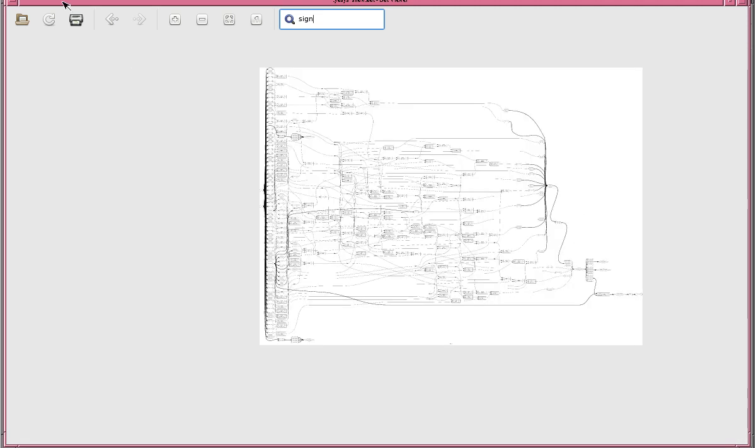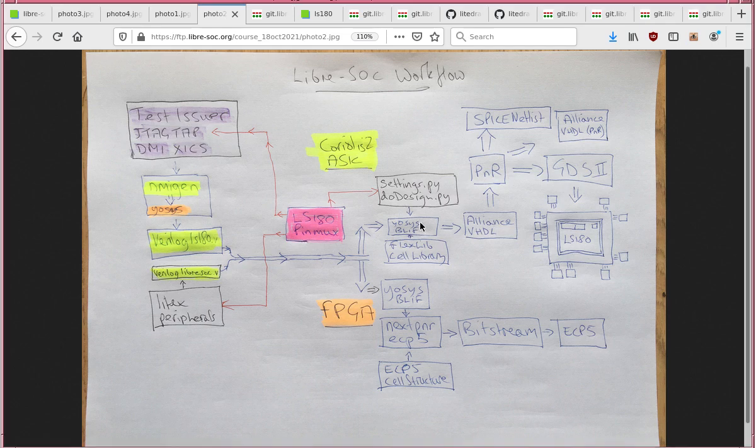And so coming back to here, what we do is we hand it the FlexLib cell library, which contains the cells that have been designed by Chips4Makers, and Coriolis with Yosys will then incorporate that and generate the BLIF file from that cell library.